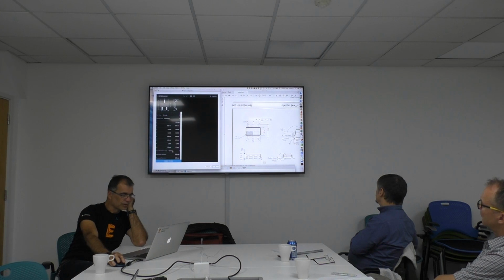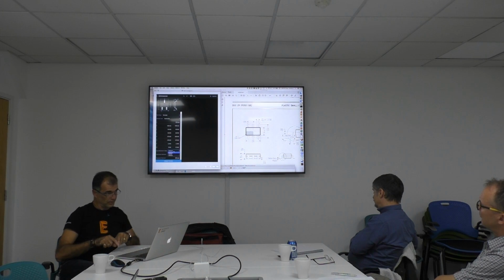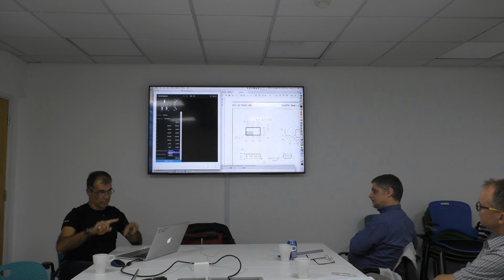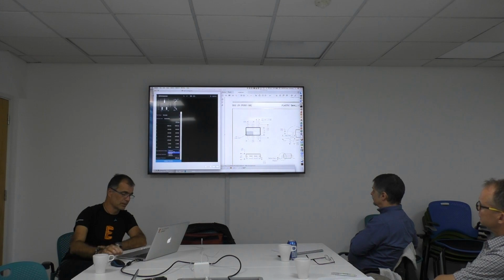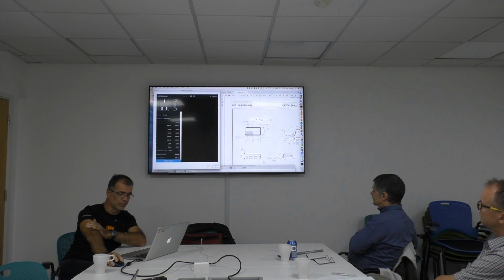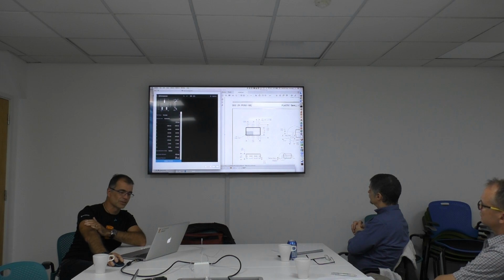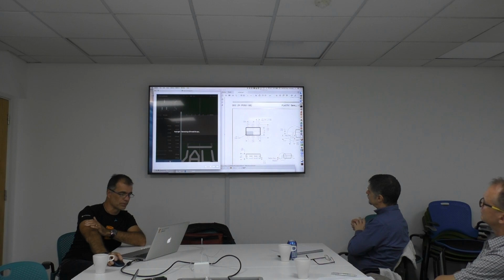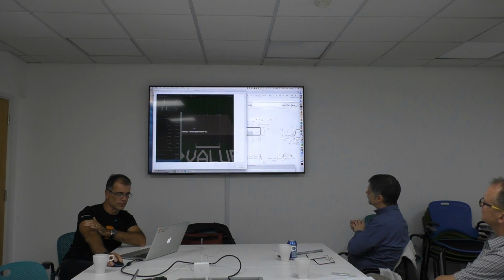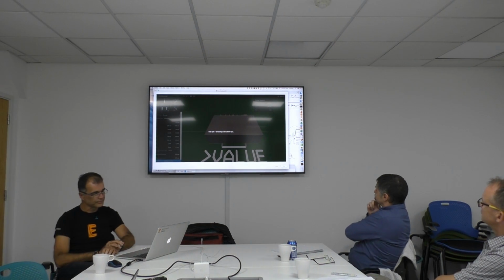Then we have match silk screen the body, so I could decide the size of the silk screen around the body, bigger or the same or less size. Normal fabrication tolerance, that's something mentioned to 0.2. I think that's not really important here, but let's click update preview. Now generate the model for us.